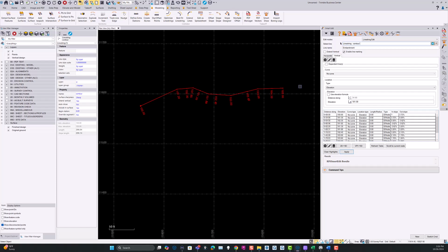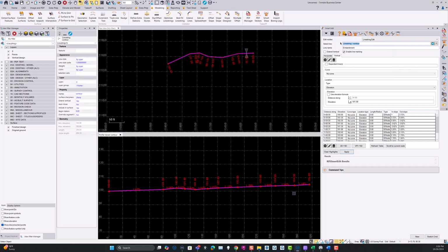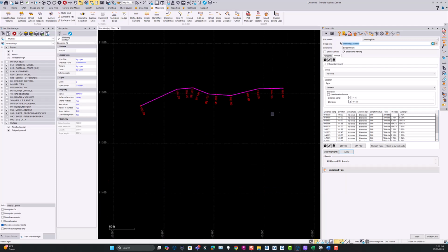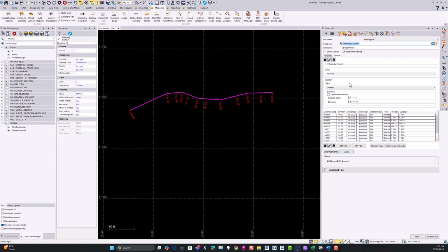And if you wanted to see the vertical profile of that, again you can do Shift M directly on here, and you can pick the profile viewer, and it will highlight that line and show you the vertical profile of that line while you're working. So keep going through here. So this is the line edit mode for vertical. So you've got the add nodes and the edit nodes.